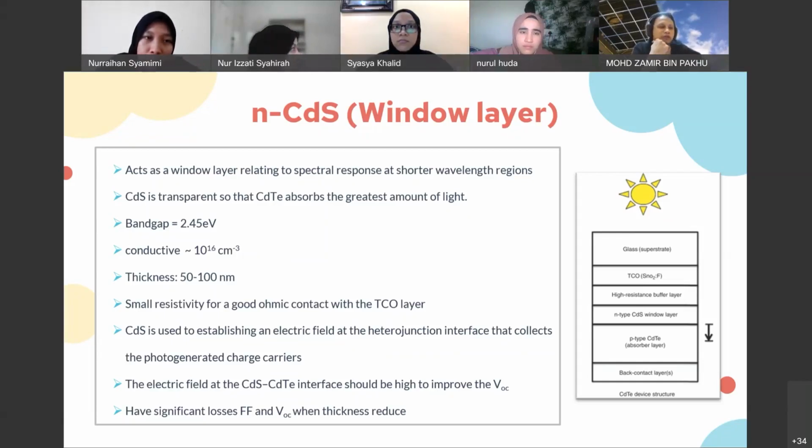If you recall the bell-shaped curve we discussed last time, a high band gap gives you high voltage but low current. A low band gap on the left gives you high current but low voltage. The optimum is in the center of the bell curve, where you get both high current and high voltage. So when you design the band gap of the solar cell, it has to be somewhere from 1 to 1.5 for outdoor harvesting. Any other questions?